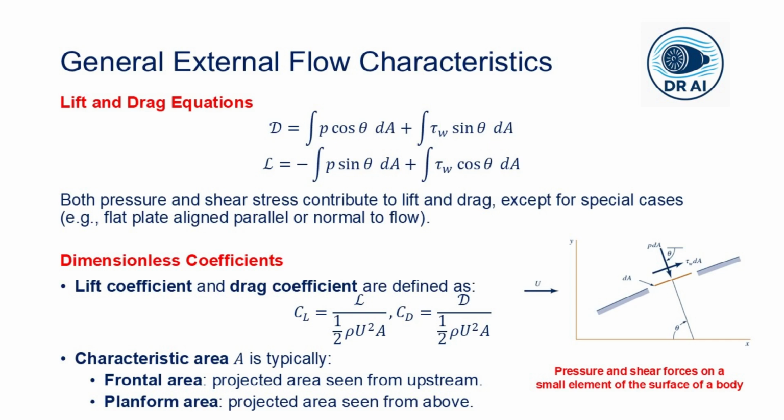So notice something crucial in this, that both pressure and the shear stress contribute to both lift and the drag forces unless the surface is perfectly aligned with or perpendicular to the flow. For a flat plate parallel to the flow, where theta is 90 degrees on the top and 270 degrees on the bottom, the pressure forces cancel, and only the shear stress contributes to the drag.